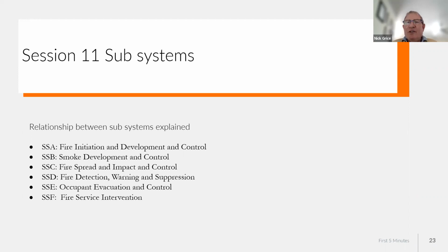There is a simple way of doing it. Engineers go in, like Nathan's been in and done a few here with me in Adelaide, and they give the building a report. And this particular one, the engineer, who's apparently a long-term associate, has said that obviously the occupant warning system was installed to the 2004 standard, and the wiring in the building is insufficient to support an extra tone. Right, so that means it needs rewiring.